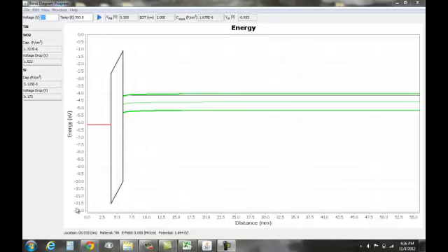One is location, the other is material, the other is electric field, and the final one is potential, which is voltage. Electric field is in megavolts per centimeter. As I hover over this particular material, it shows that it's titanium nitride, which is a conductor in this case. If I move my cursor over to the next material, that is silicon dioxide, it shows a constant electric field as I move across, but you can see the potential is changing.